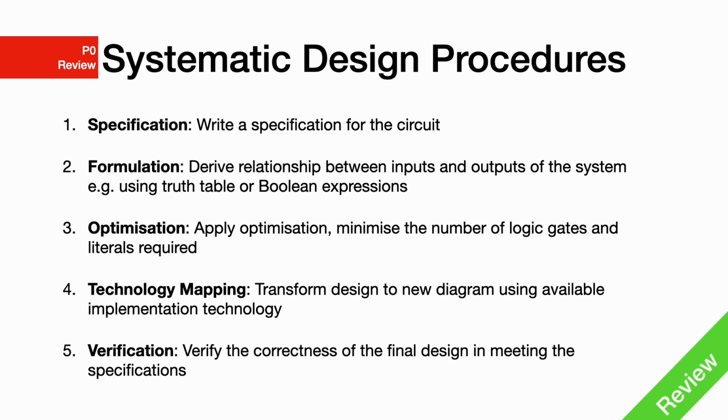It is very important to note that certain technologies will only be available to you at the step of technology mapping. So in cases where you want to use hierarchical design, when you're doing the optimization, your hierarchical design is only half completed, and you have to first of all start with defining all of the functional blocks you need and implement them as technologies. And only until then will you know how to optimize the overall circuit. So in certain cases, it is possible that you would need to go back and forth between optimization and technology mapping, depending on the circumstances at hand.